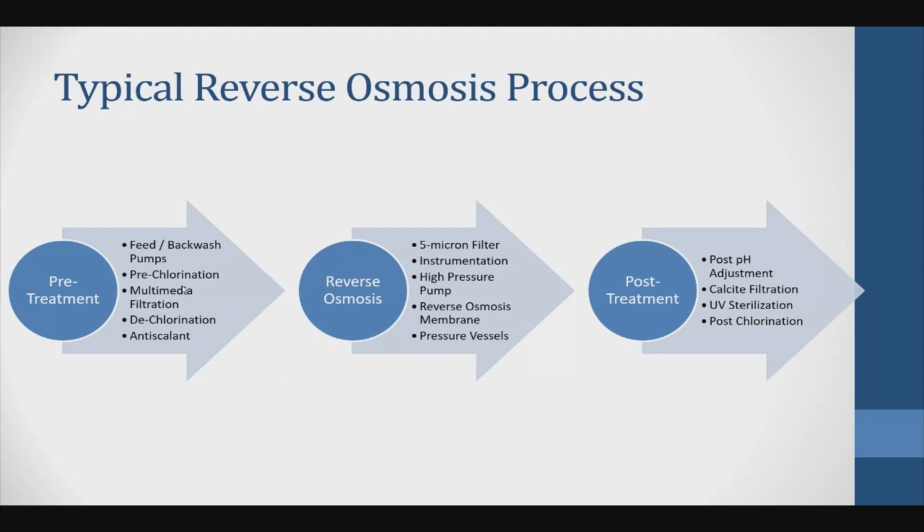And another definition, where membrane manufacturers would like to have the water quality, as a turbidity measure, to be less than 3 SDI. SDI means silt density index. So if it's higher than this, it's going to cause a lot of problems for the holes or the openings of the membranes. Now, most of the membrane companies would want the OEMs to bring down the quality of the water to less than 3 SDI.